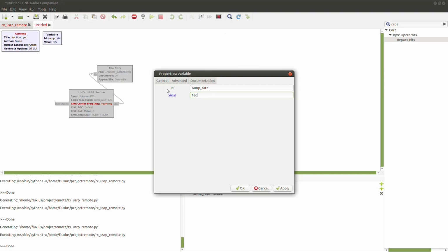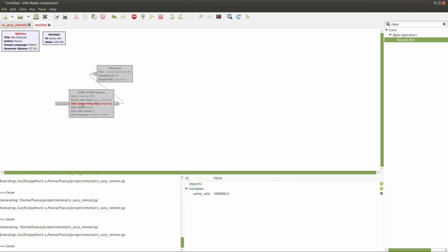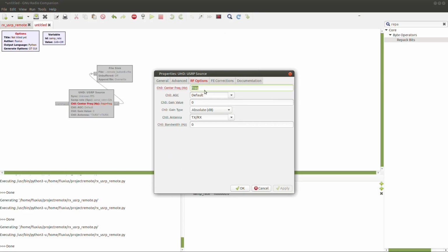Sample rate 1 mega, like that. Okay, so here I'll just specify directly the frequency, because I'm lazy, and the gain value, and that would be that. Okay, yeah, I could also use another gain, because this is also why the signal is pretty low. I can use another gain which is maybe better for the reception, but still I have to be very cautious about that.